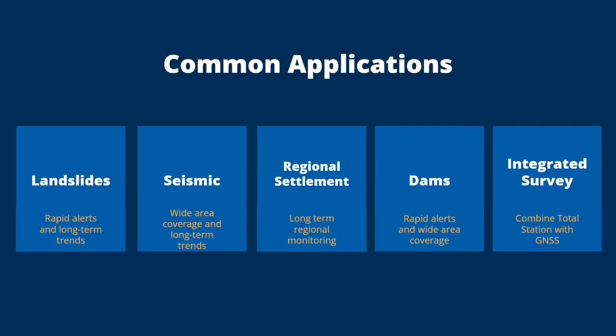Dams are another common application, especially when we talk about large tailings dams or concrete structures, where we need that rapid alerting. So we expect that the dam really doesn't move at all until it moves quite a bit. And so we really like to see that, again, combination of long-term post-processing high precision with that rapid alerting. Dams tend to also be very high risk, and so it's really important to alert the second that some movement happens. So having that real-time processing and that 20 hertz tracking can be extremely important.